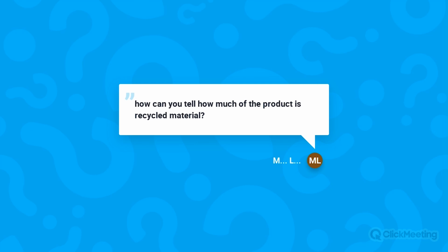In the previous webinar that we did, we showed that we could track, even though you had an inventory which was a mixture of NPK 20-20-20, it was equivalent to urea, KCl, etc., P2O5. It's just because of the name of the material. By giving a material property, which is its name, when we run the mass balance, we know the fraction of the material which is passing through. So Sigmafine sees it as a material. In the material tracking, it sees it as urea, and it sees it as biomass, and it sees it as P from P2O5 and P from bone meal.